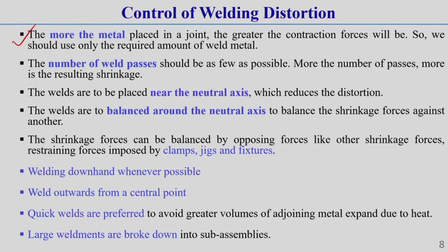So first of all, what I have told you, for controlling of distortion we know that the more the metal placed in the joint, the greater the contraction force will be during solidification. So always keep this in mind, we should use as little weld material as possible, but we should use such an amount of weld material so that our requirement is fulfilled, that means it should have sufficient